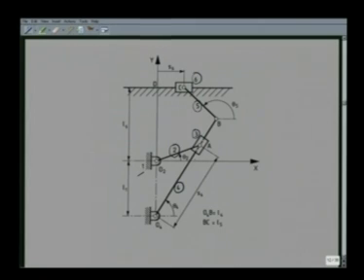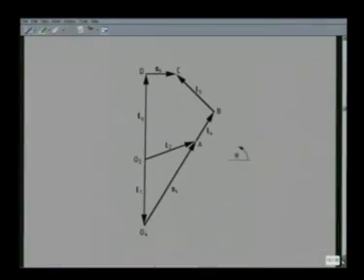So, to do the kinematic analysis of such a mechanism by analytical method, let us first identify that there is more than one closed loop. We draw all the link lengths by the corresponding vectors, like L2 is the vector which represents the second link O2A, L1 is the other vector which represents the fixed link O2O4, and O4A, that is the slider displacement, we use another vector, namely S4. Similarly, the slider displacement we represent by another vector S6, and O4B is the other link vector.